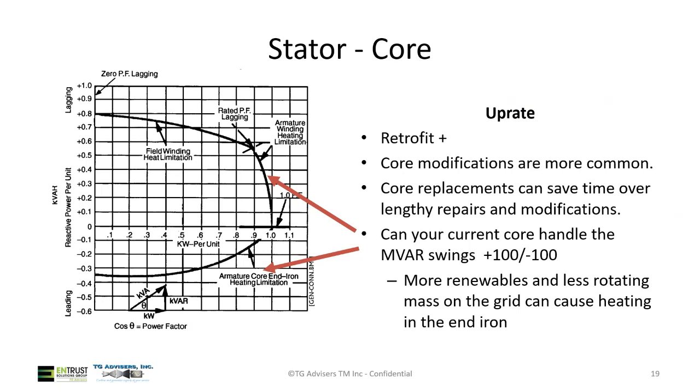On the vertical axis, you have your VAR loads, and on the horizontal axis, you have your output, the power that you want to make, because that's what you can sell. The place you want to operate is right on that line. You get the most output, and it's the easiest on the generator to handle. That's where you make your money.